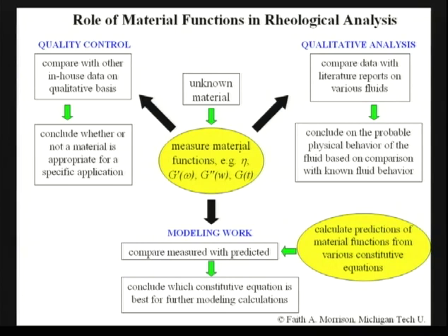There's actually a subtle meaning difference between viscosities. This is the non-Newtonian viscosity. This is the general viscosity, whereas what we've been talking about is the strictly Newtonian viscosity. But there will be other material functions that are based on stresses and based on particular flows. And these are some of them, G prime, G double prime, and the relaxation modulus, G of t.